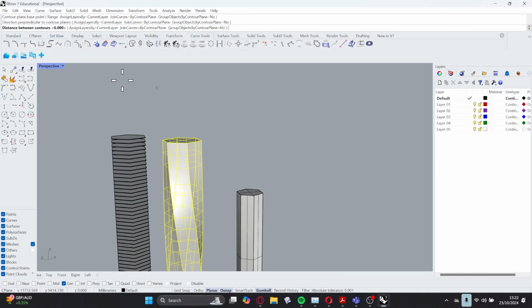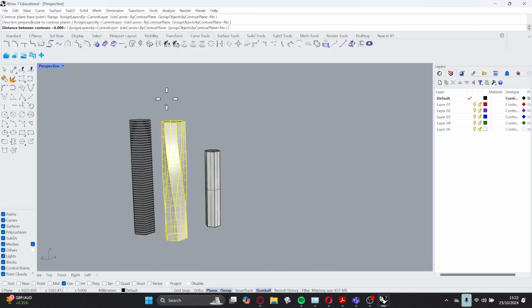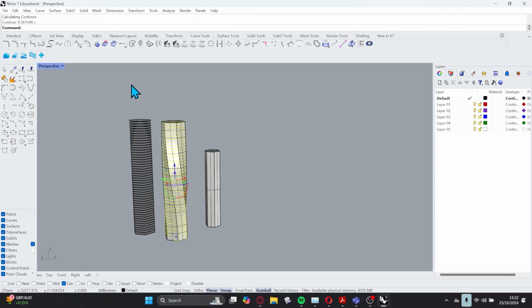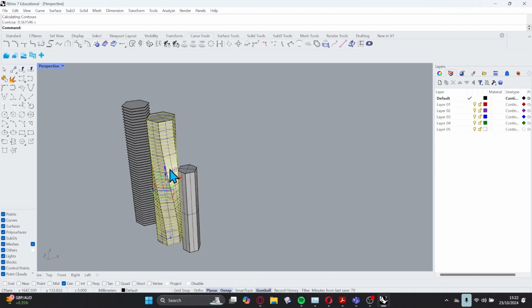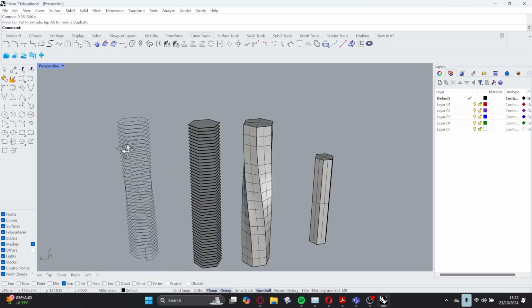And then it's going to ask for the distance that you want them to appear. I'm going to just leave it at 6, because that's what we had before. Or maybe I'll do 7.5 this time. And then it'll just run that command and contour. Did it work? Do you want to have a go? Have a go at doing it, and I'll come around and make sure. So that's how we can create our contours from there.